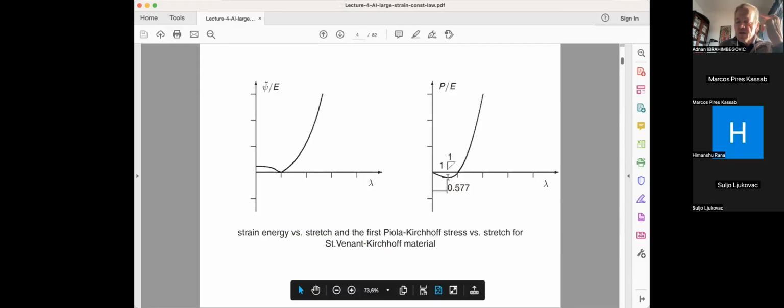And so up to then, let's say, constitutive model, even if it's not measured the same way the strain in compression and tension, you can still say, okay, I can live with that. But after that, definitely I can no longer live with that, because it goes berserk. It is not physical that you can have a very large compressive strain with a 0 stress. That just doesn't exist. It's just a basic consequence of a not well-founded formulation of this.